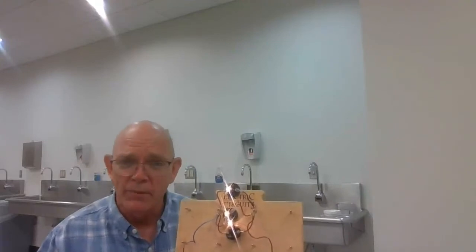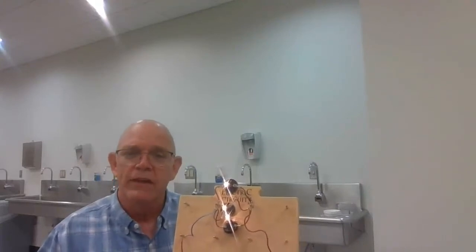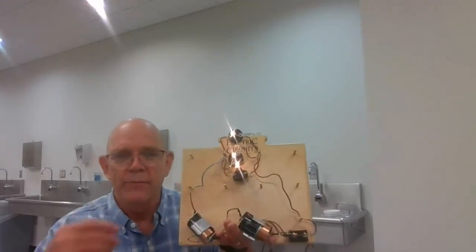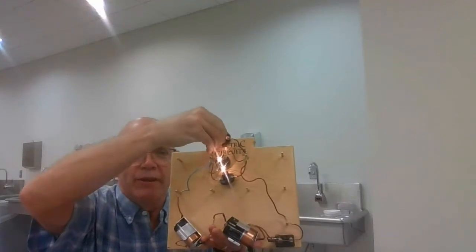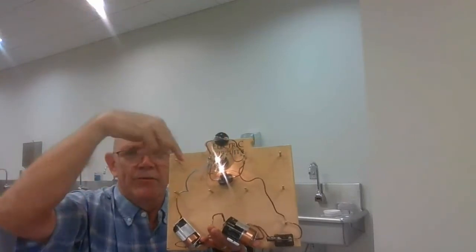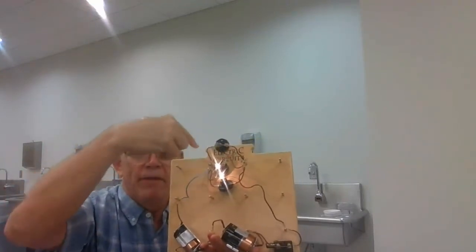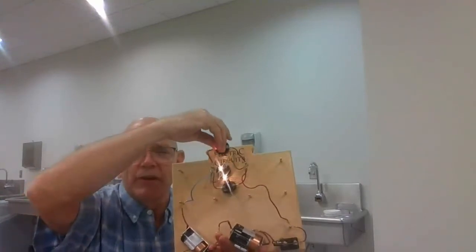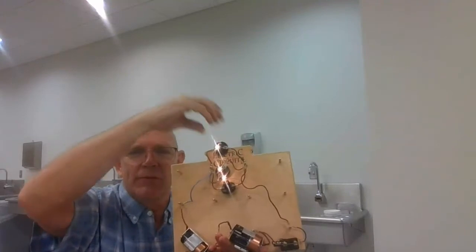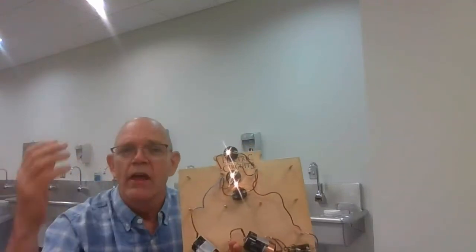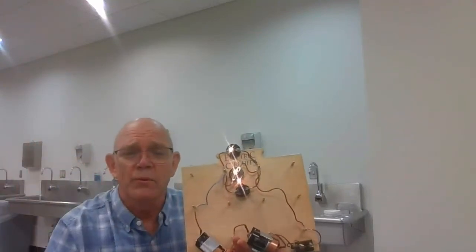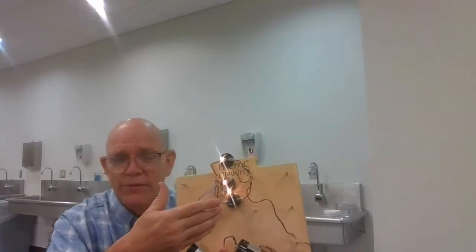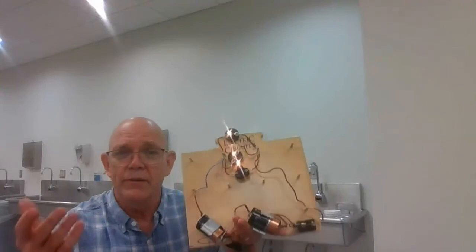Okay, instead of splitting it between the 3 like we did on the other ones, now they're all getting the full amount. So I said, well, that's good. And there's some other advantages. If one of these goes out, well, that means electricity can't go through the top path anymore, but it can still go through the other ones, and you'll notice that they're still just as bright as they were before. And when I screw that one back in, it doesn't affect how bright they are. Okay, so they're still getting the full voltage. Okay, and if they have the same resistance like this, they're also getting the same amount of current.